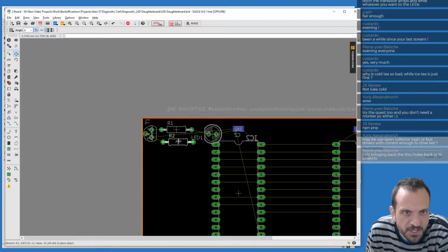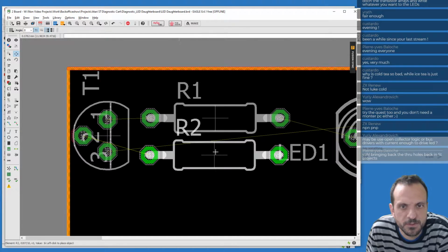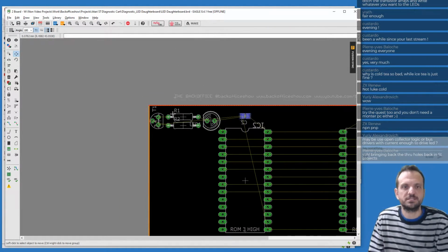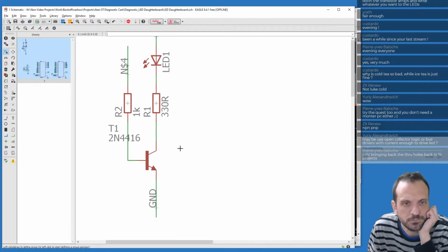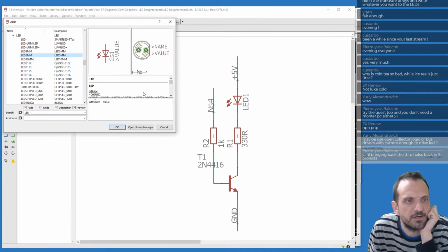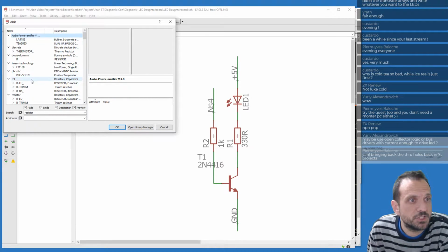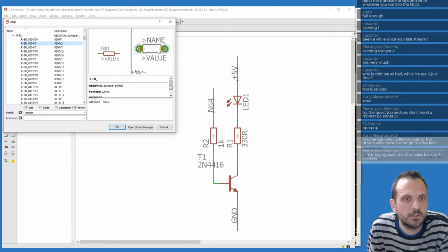Now, those resistors, I think we could probably find a better footprint. What's my grid spacing even? Look at the grid spacing. So you could fit something like that. If we can get smaller resistors, I think you can get that all in quite neatly. So we'll try that. What resistor footprints do we have? Does it have the wattage? I kind of feel these are too high a wattage. So just type 204.